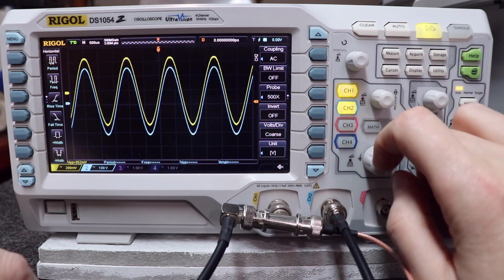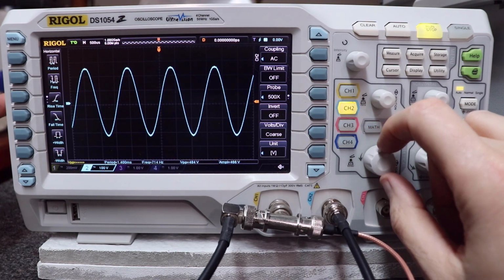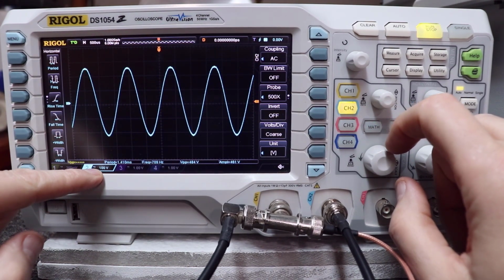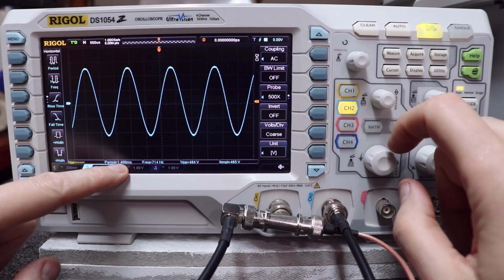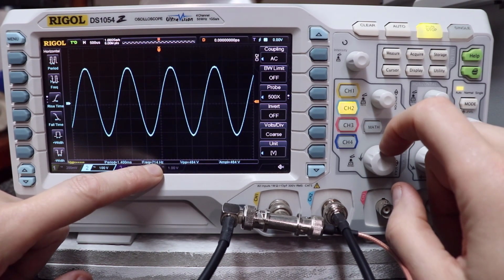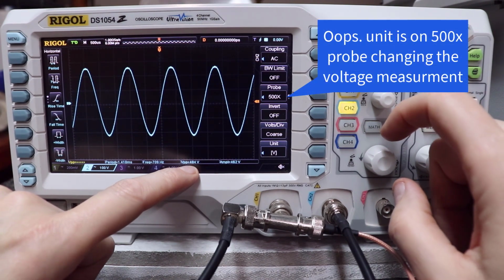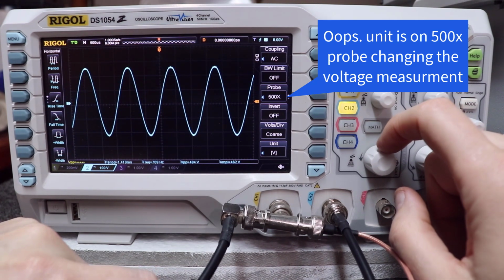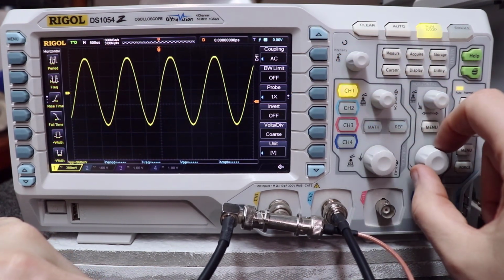You can also turn it on channel 2 here. See the other signal, turn channel 1 off, right? There again, VPP on this 100 millivolts right here. I can also see, what do I see here? The period, the frequency. I'm on 712 or 714 hertz right now. My VPP, 484 millivolts here at this point in time. It's just the same, okay?